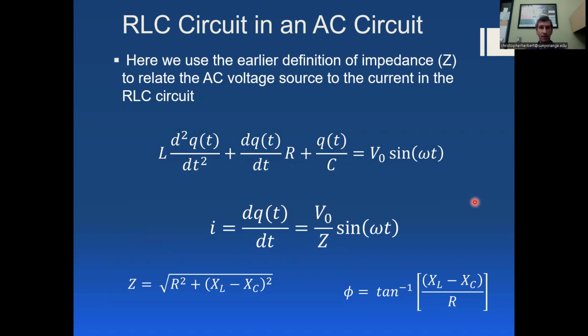They're basically trading energy back and forth with their electric and magnetic fields. We can see in the equation for impedance that when XL is the same as XC, those are the reactances for both the inductor and the capacitor, this term basically goes away and all of our impedance just becomes due to our ohms from our resistor, our ohmic losses here.